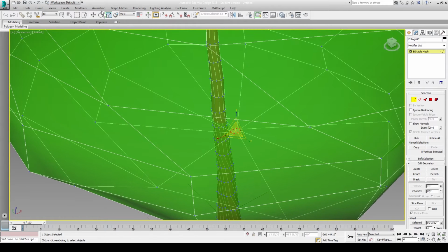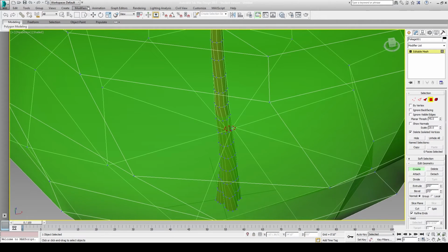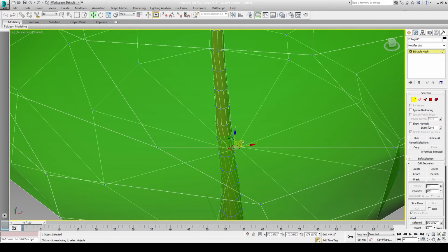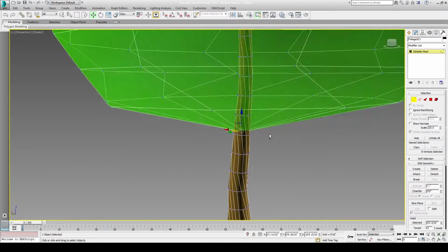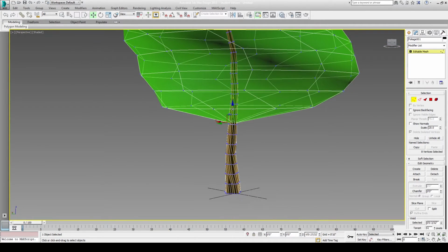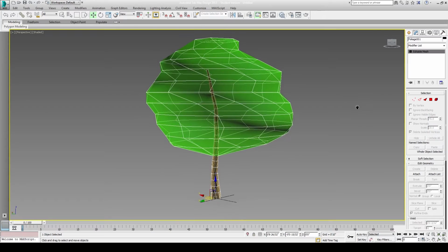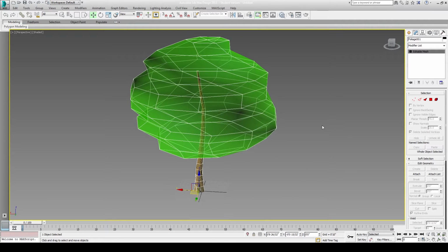And I'm going to move them so that they happen just inside of the trunk. I accidentally deselected them there. There we go. Great. And the last thing I'm going to do is move them down so that my slope isn't too severe. I know that my Replicator 2 will easily print this trunk, and then it will start growing up at an angle to print the rest of that tree canopy. So really, really simple. Scale it in, move it down just a little bit, and this is ready to print.